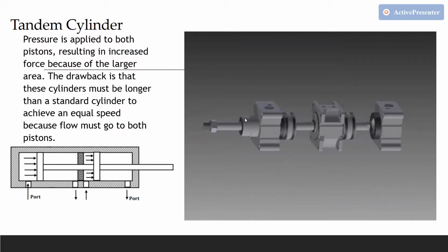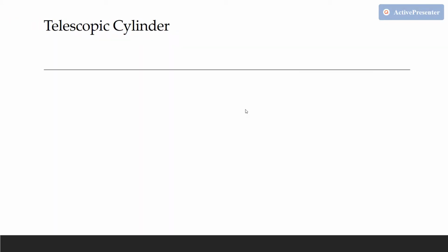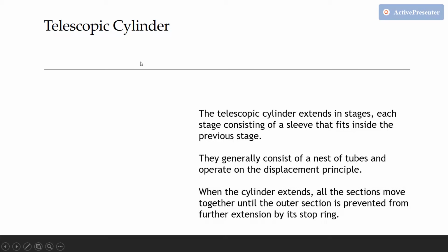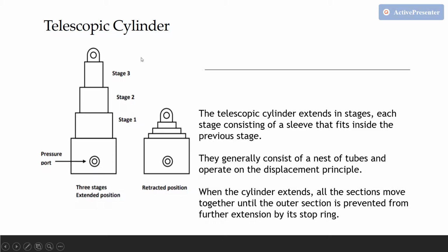Now we come to our next topic, the telescopic cylinder. We can use telescopic cylinders when we need a long stroke length and a short retracted length.